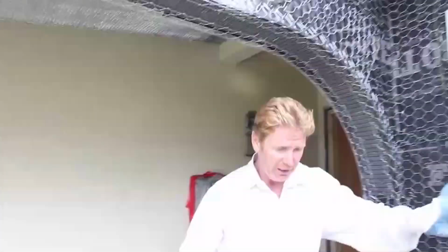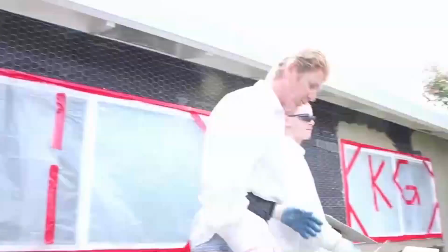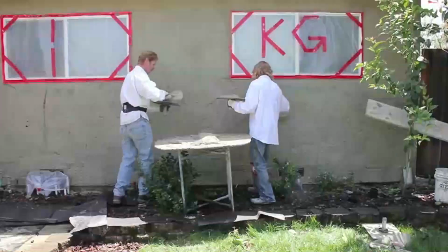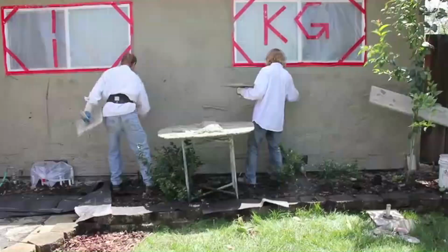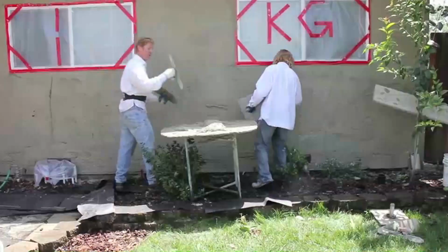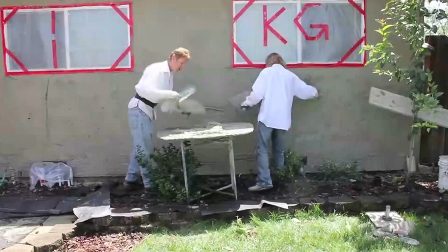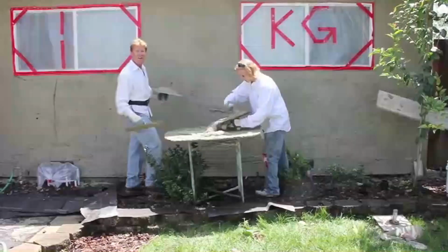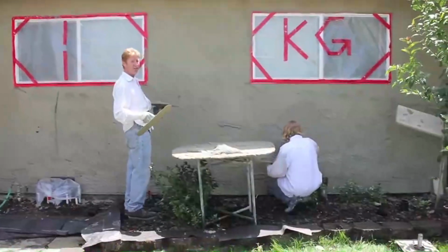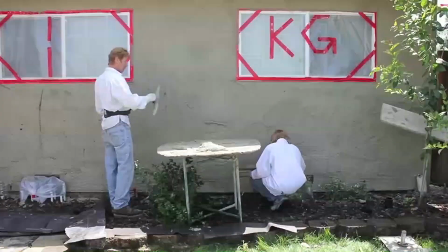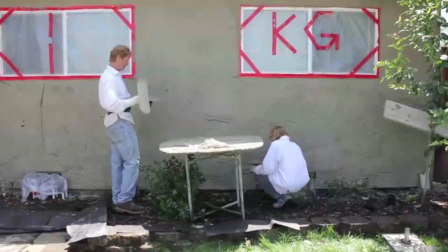We're going to go ahead and scratch the entire thing, and when we're done with scratching the entire thing, we're going to start browning these. All right guys, second coat, fat and ugly. I'm going to derby it. That means I'm going to take a rod to it, a feather edge, a rod, a T-bar, depending on whatever country you're in. In Australia, they keep calling them T-bars or straight edges. Once we put the second coat on, I'll show you how we work that.